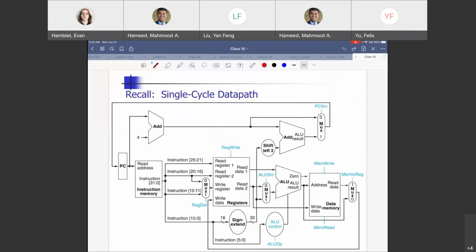So this is a quick recall. This is the single cycle data path. It supports the 5 steps, right? What are those? Fetch instruction, decode instruction, fetch operands, execute instruction, and then housekeeping, increment program counter by 1. So it includes all of that. Starting from instruction memory, you're going to read the instruction, whatever that instruction is, identified by the program counter.